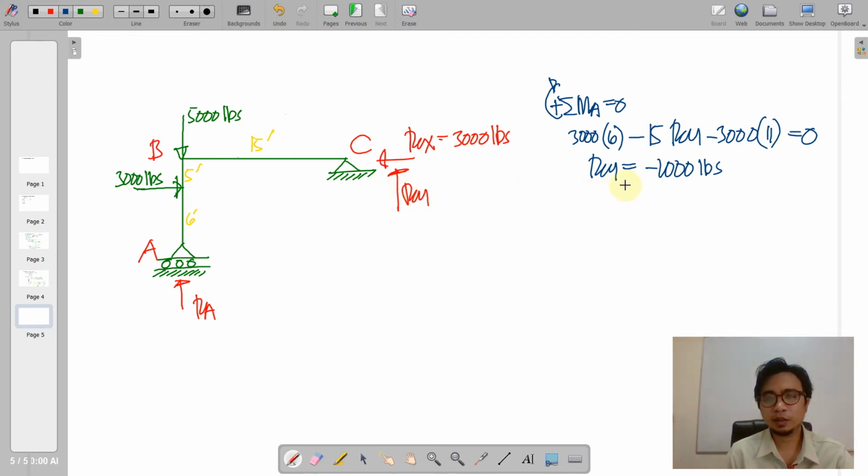So anyway, we'll just maintain here the same figure, but in our analysis along, we are going to always carry the sign here and first maintain the direction. So we take moments at C here, and we have counterclockwise 5000 times moment arm of 15.